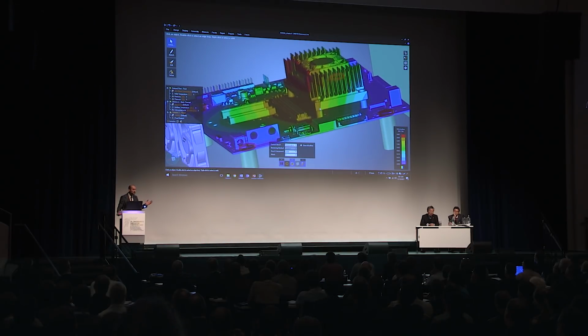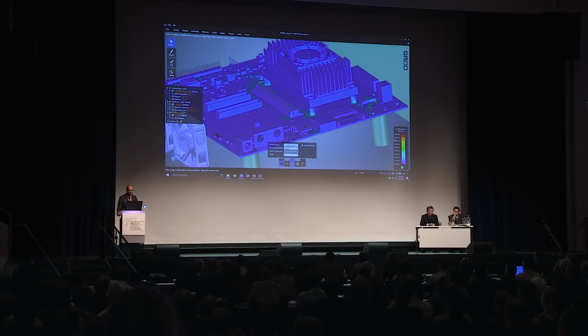Now, seeing the modes is useful, but another thing that's useful as a design engineer is being able to look at the location of stresses caused by that mode. There are tons of displayed results that you can choose from here. Let's pick another one. Let's go look at that stress. And again, we can choose to exaggerate it, right? Here, let's say we do something like this.